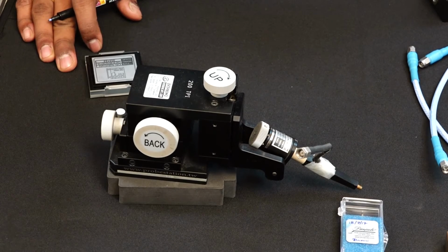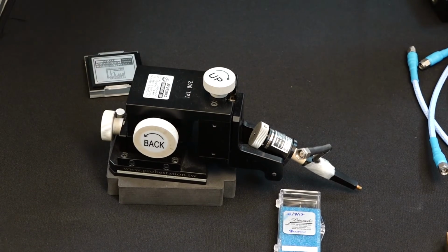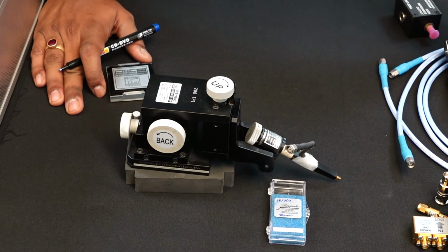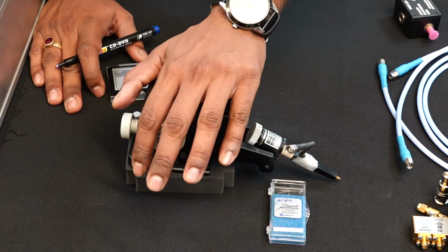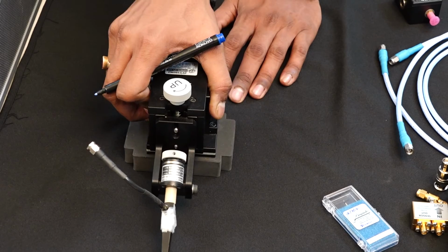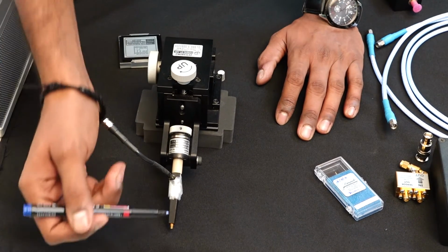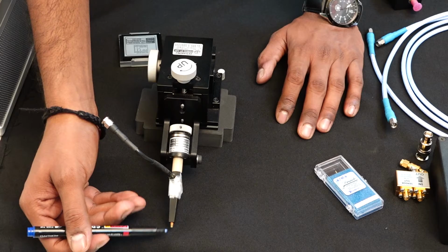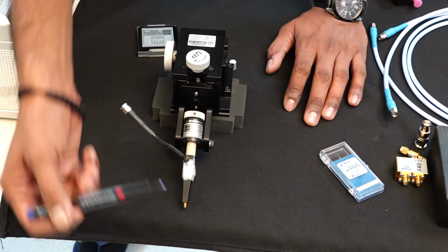Now that I've talked about probe tips, as you can think, probe tips are not hanging, right? They're connected to the whole setup through a set of probe arms. This is one of the probe arms that we use in our measurements, and we have more like this. What you do is connect the probe tips here at the end of the probe arm, and then this goes to the device under test, say here.